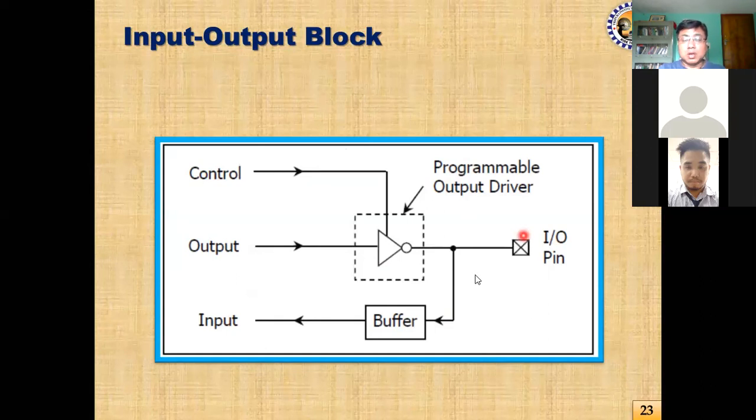Now we have seen, even in the case of PAL16L8, that there are certain pins which can perform dual function, input as well as output, right? But at a time it performs only one function. If you want it to work as input, it will work only as input. If you want it to work as output, it will work only as output.